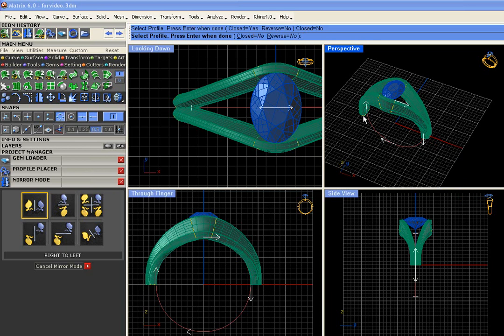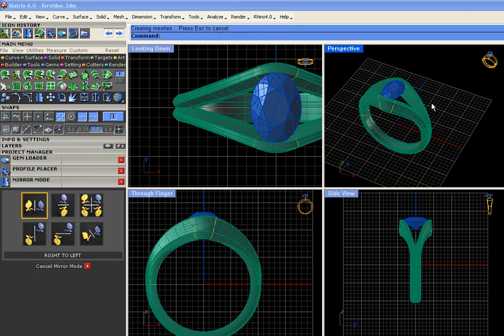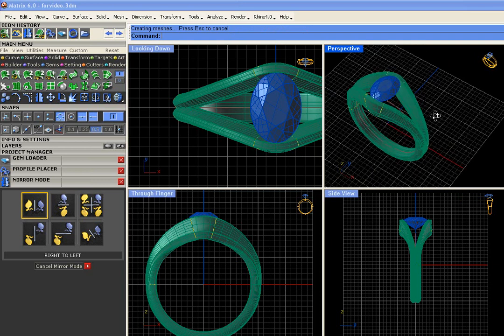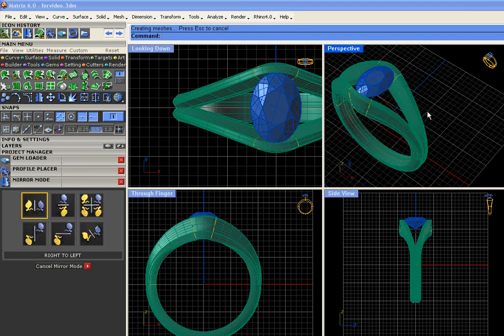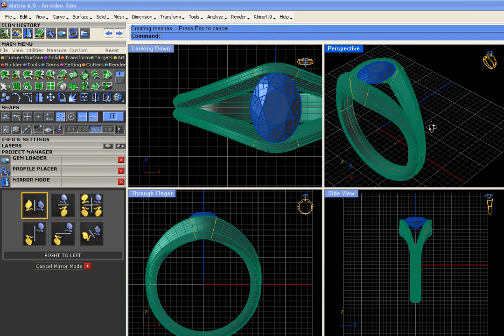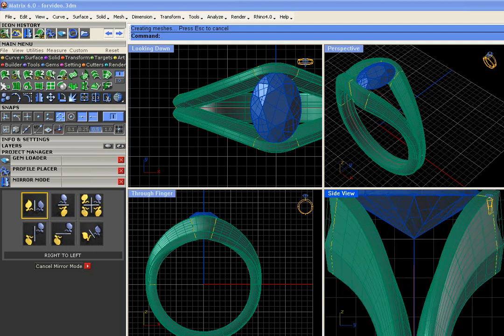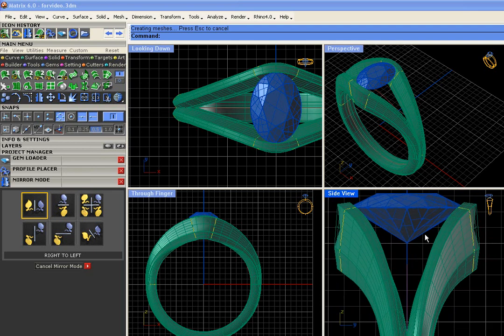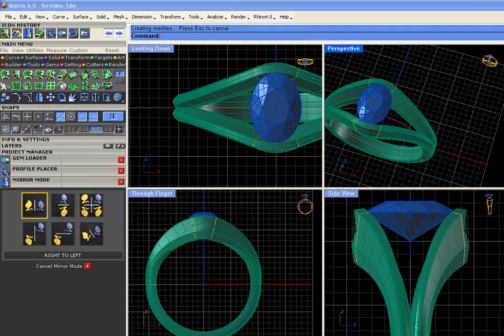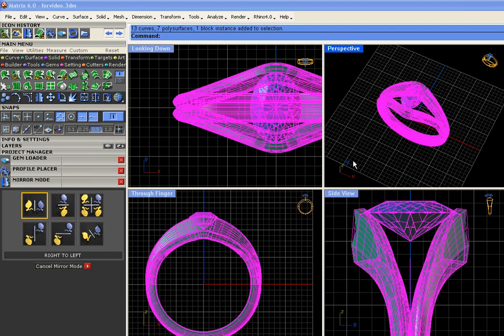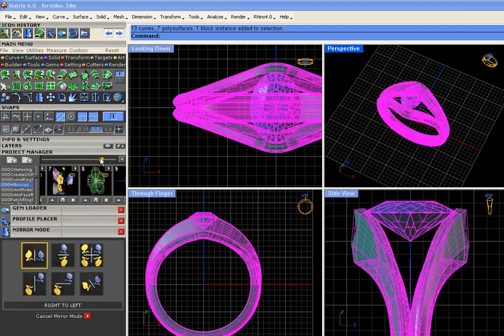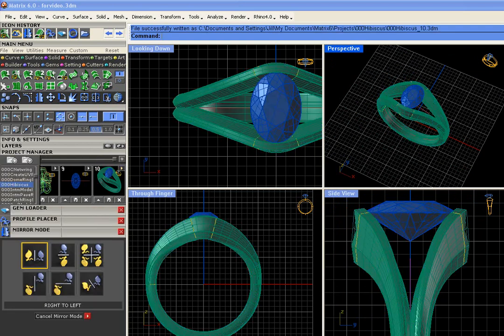Close equals no. And there's our design. The last little version 6 tool to teach you with this ring, which is really a great trick, is the tapered baguettes between two curves. You can put out any two curves where you want the tapered baguette to be, and then you get all the baguette builder controls right there at those curves. So let's stick this in a job bag and show you the last part of this little demonstration.